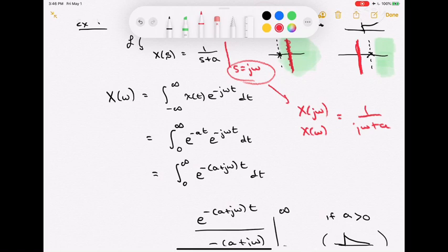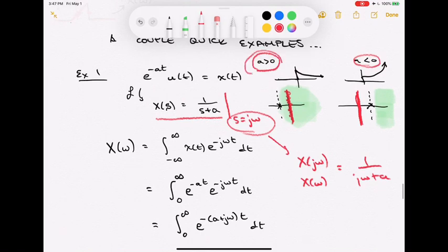There is a tight connection between the Fourier transform and Laplace transform. Now, the Laplace transform always has a transform for this signal, regardless of whether a is greater than 0 or whether it's less than 0. All that happens different there is that the region of convergence just keeps moving, right? It keeps moving according to wherever the root was.